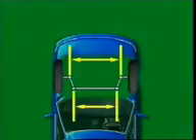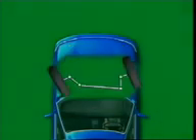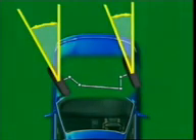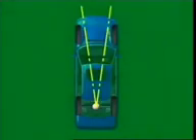Because the rear wheels are fixed, the centre of turn will lie somewhere along the centre line of the rear axle, depending on how far the steering wheel is turned from the straight ahead position. To provide true rolling motion, the inner wheel must be turned through a greater angle than the outer wheel. This allows the inner wheel to turn through a smaller turning radius than the outer wheel. This automatically correct alignment is obtained by use of the Ackermann principle and layout.